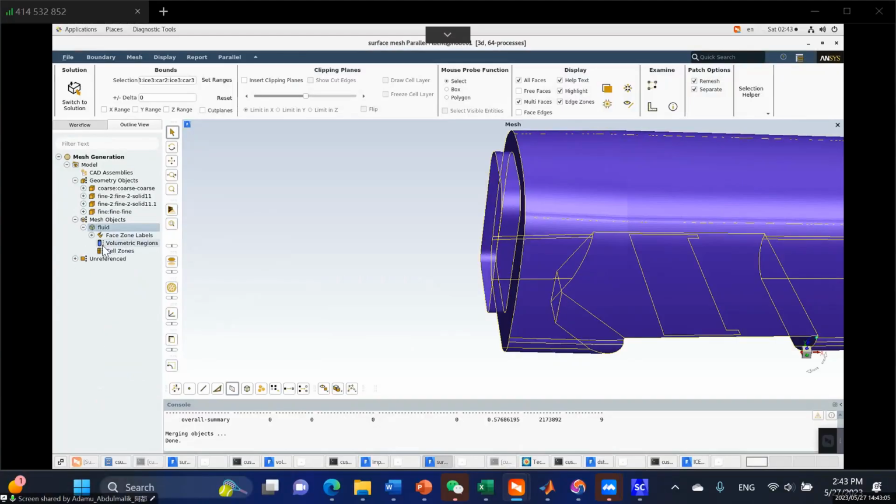So what I want to do is to right click on these volumetric regions because I want to divide these regions, what is solid and what should be fluid. Inside the computational domain, it's supposed to be fluid, it's supposed to be air, right? Then the train itself should be a solid body. So I'm going to separate them. The system is going to identify if this is a solid or a fluid region.